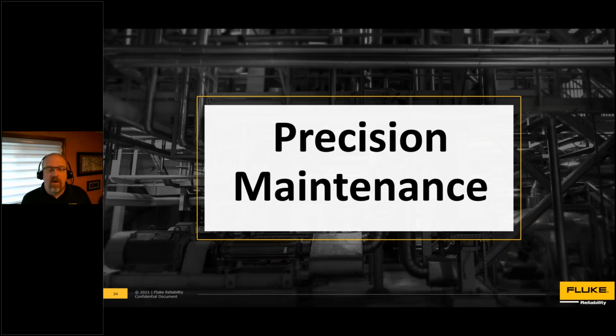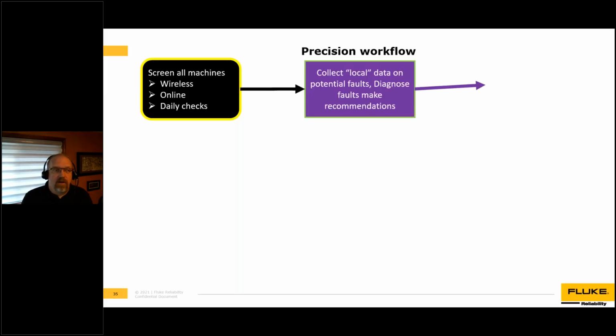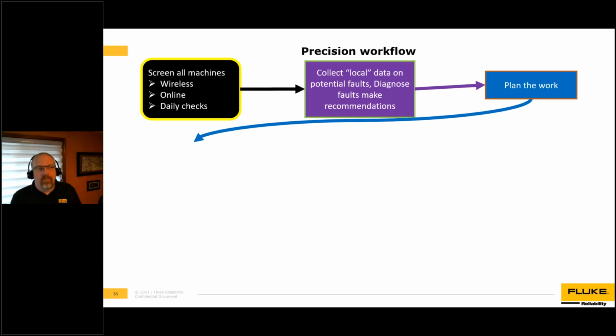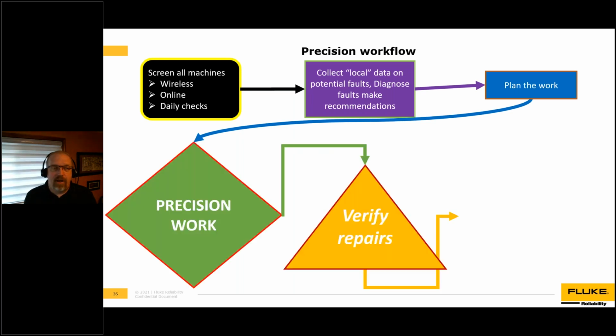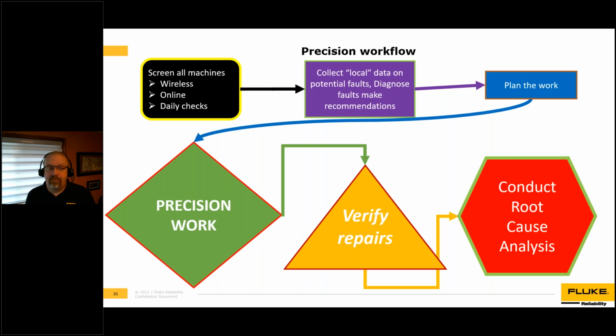So we discussed what's changing and improving in the world of vibration analysis, and now let's talk a little bit about what happens after you've collected the data. First, you need to do your screening, and this may include enabling your operators, making their daily rounds more productive, maybe giving them a little bit of training or simplified tools like those IR thermometers that I mentioned earlier. You're going to go through the alarms that your screening has produced, and you're going to verify your potential faults.